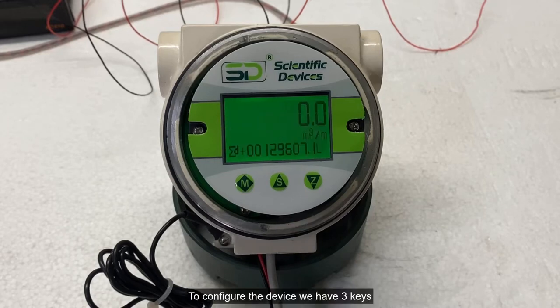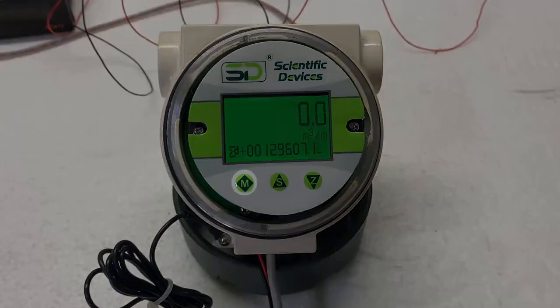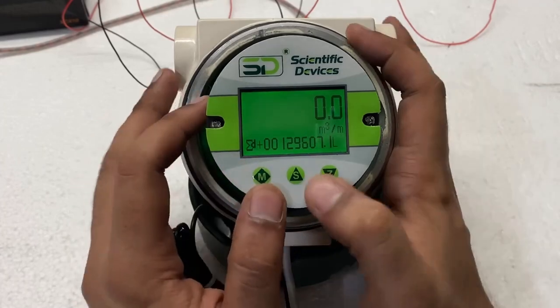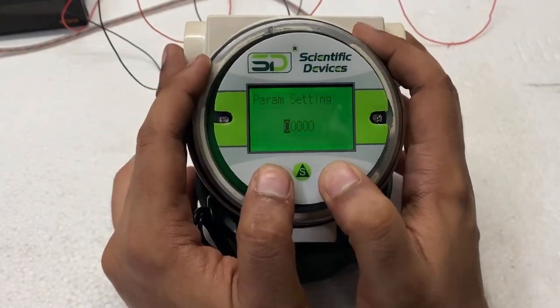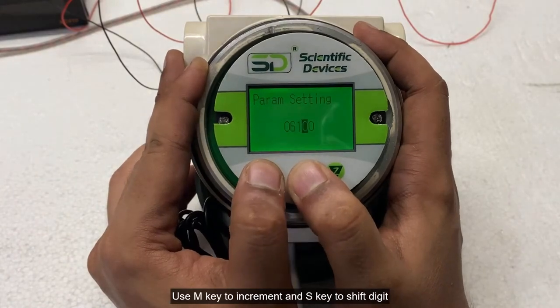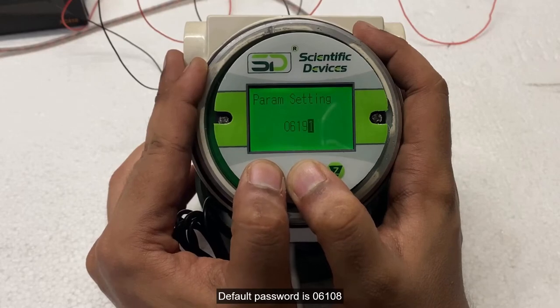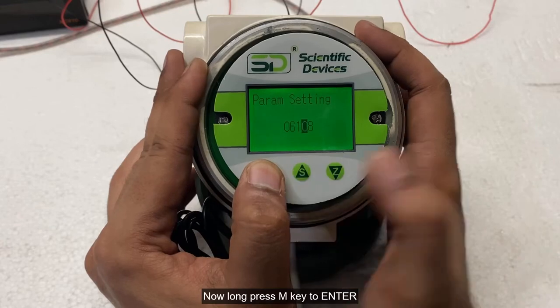To configure the device we have 3 keys: M key, S key, and Z key. Long press Z key to go into the menu. Enter password for parameter settings using M and S key. Use M key to increment and S key to shift digit. Default password is 06108. Now long press M key to enter.